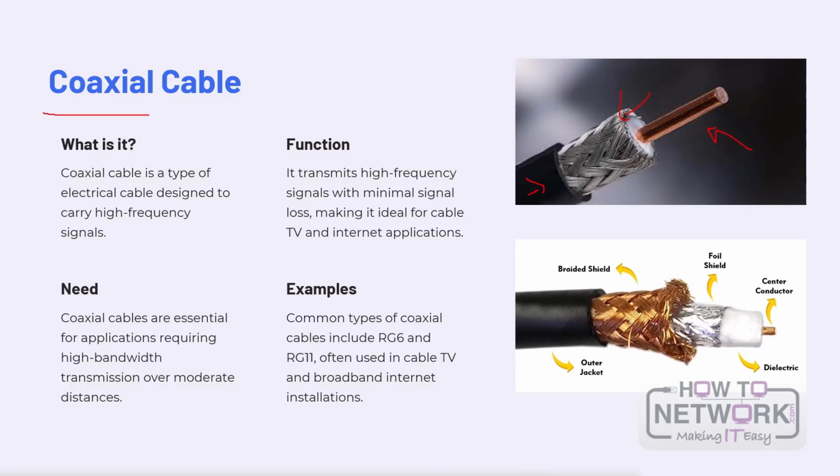The cable's design effectively mitigates signal degradation caused by electromagnetic interference, or EMI, and radio frequency interference, or RFI, ensuring reliable signal delivery. Then the braided shield acts as a Faraday cage, this one, which effectively blocks external electromagnetic fields from impacting the signal within the cable.